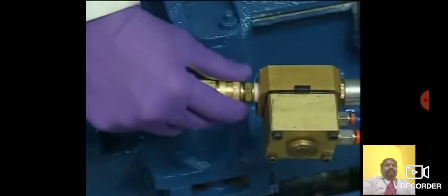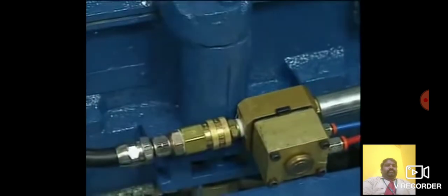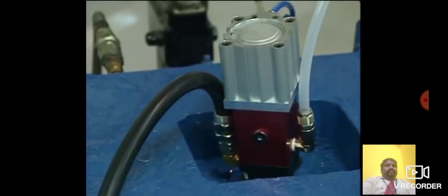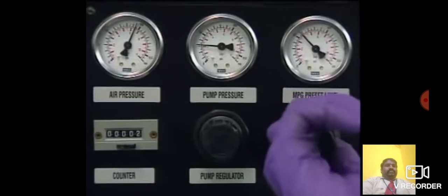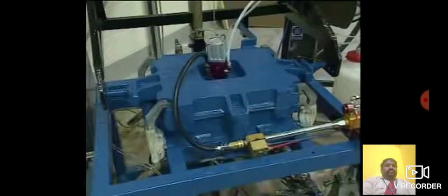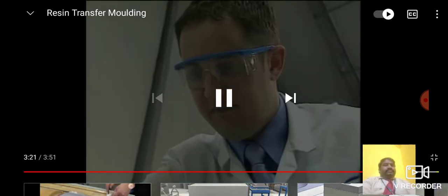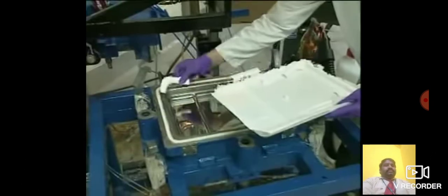Further automation can be achieved using auto-screw technology. This valve is built into the mold and allows simple connection of the injection machine. At the end of injection, the auto-screw automatically flushes the machine with solvent, and then the machine can be easily disconnected. Once the part has cured, it can be demolded, leaving the mold ready for the next component.